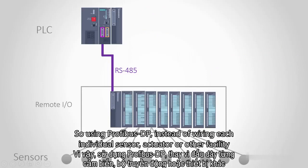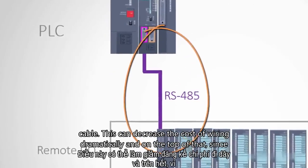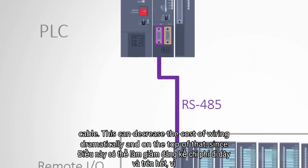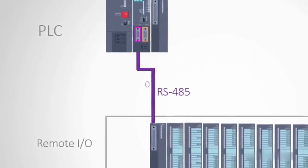So using Profibus DP, instead of wiring each individual sensor, actuator, or other facility to the PLC individually, we can install a set of remote I/Os next to these facilities in the field area and then transfer the data to the control area using a single RS-485 cable. This can decrease the cost of wiring dramatically, and on top of that, since the data transmission method here is digital, industrial environment noise has less of an impact on data, so data communication between the control and field areas will be more robust.